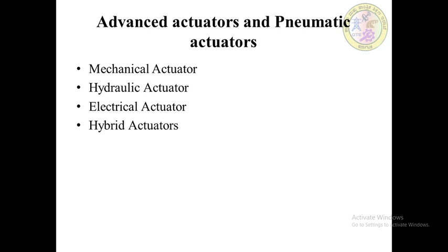If you come to a hydraulic actuator, unlike air, liquid cannot be compressed, we know that, and hence hydraulics generate higher energy than any other system, which is operated at a high pressure range. Systems involving high load are operated by hydraulic actuators, in which the oil pressure is applied on a mechanical actuator to give the output in the form of rotary or linear motion.